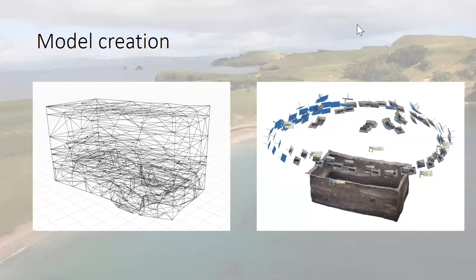In the case of the SLAM and the photogrammetry data, the models of two deposits that were superimposed were aligned, and then the extraneous area of the bulk above that layer, if there was any, was cropped out before they were merged and then brought into Blender to basically use an octree filter to remesh the entire trench into a coherent volume. And that was octree level 8 for anyone that was interested.